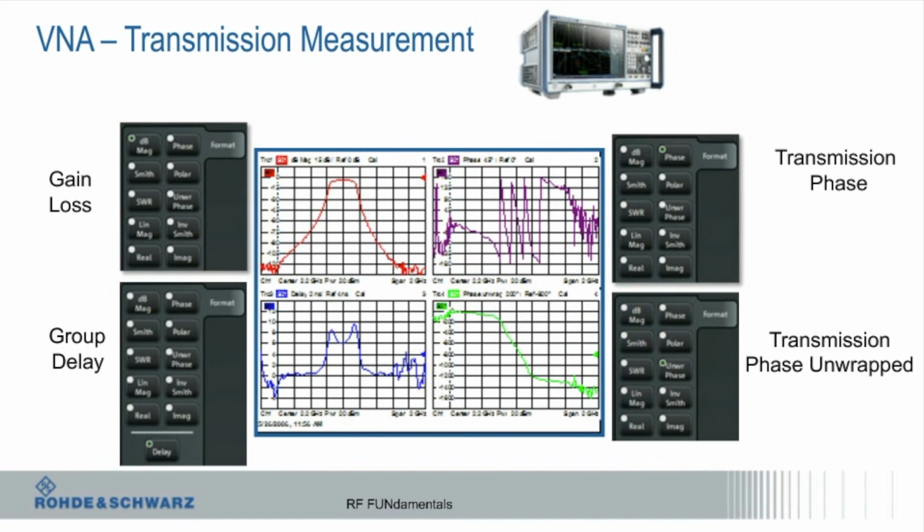So, transmission measurements. Those were reflection measurements, and I was looking at S11, but it could just as soon be S22. Now I can look at gain and loss. So this is like frequency response.